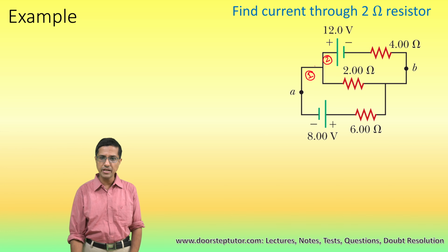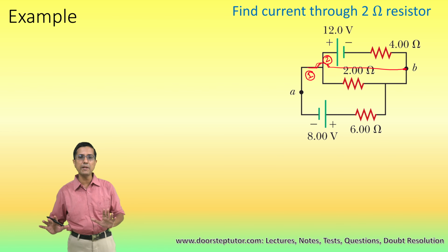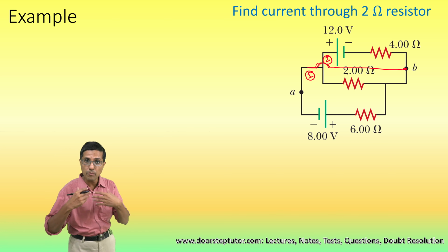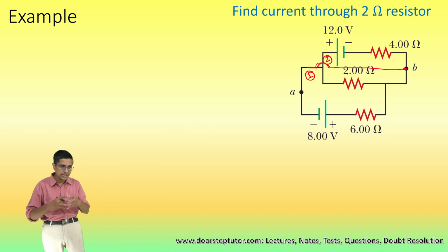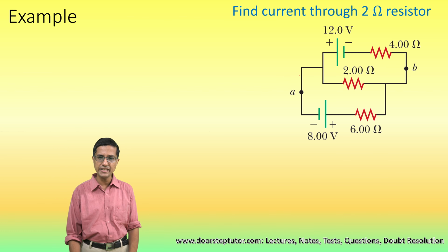There are no wires jumping around, right? For example, a jumping around wire would be this wire, if it went around like this and then got connected here, then this wire is actually going out of the nice 2D plane, it's jumping out. And in this case, I cannot use the mesh rule. I would have to go back to my original Kirchhoff laws and then assign all the currents that I possibly can, and solve all the equations. But provided that our circuit is actually two-dimensional, 100%, no jumping of wires involved, then I can use the mesh method to actually simplify my calculation.